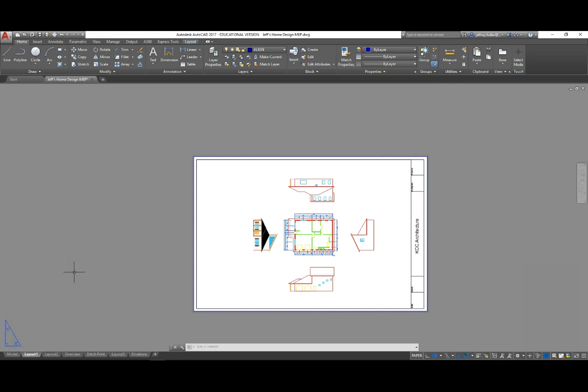Now the setup is pretty much complete for this sheet. Next, you're going to create layout number 2 on your own. Layout number 2 will be of just your floor plan, showing all of your dimensions. Electrical, furniture, appliance, and casework layers must be turned off. The next video will show you how to put multiple viewports on the same drawing to show your elevations on the same sheet.